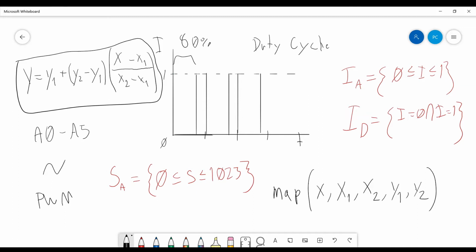It can be 80% of the time on. It can be 70% of the time on. This is what pulse width modulation is. That's how the Arduino distributes an analog signal. You see? That being said, let's do this on the Arduino and code it out. I got some things I want to teach you.